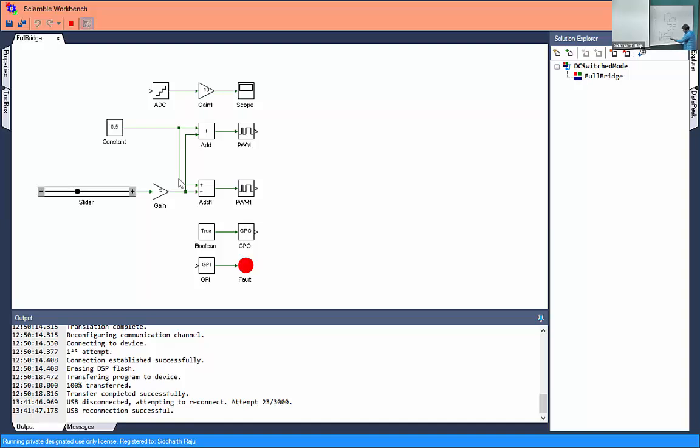And this itself is the total time period, T period, and this is equal to 1 divided by the switching frequency, FSW. If you have these repeating trains of pulses, you can get the switching frequency of the converter by figuring out how long a full on and off cycle lasts, and that gives you your switching period and switching frequency.